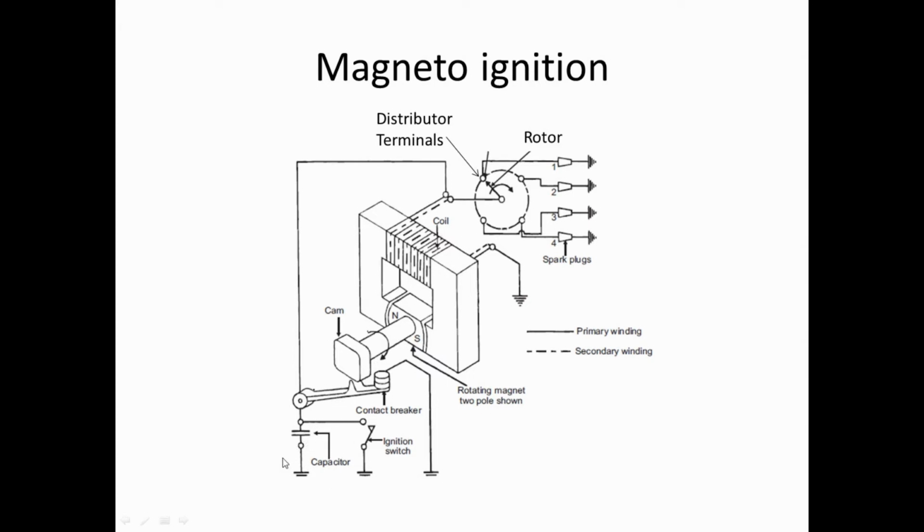Again, the capacitor, same thing. The capacitor is basically your condenser, and your ignition switch. In this case, this system actually works by opening the ignition circuit, which allows the whole system to generate electricity. When you close that ignition switch, you're grounding out your points, basically dropping your magnetic field and no spark occurs. This is kind of how a lawnmower engine works in the same principle, except the rotating magnets on the flywheel. By grounding out the ignition system, it stops the engine from running.